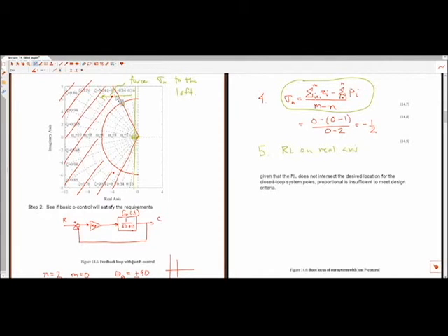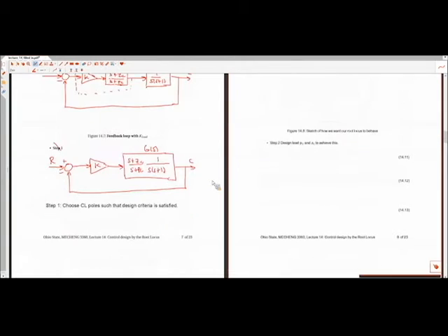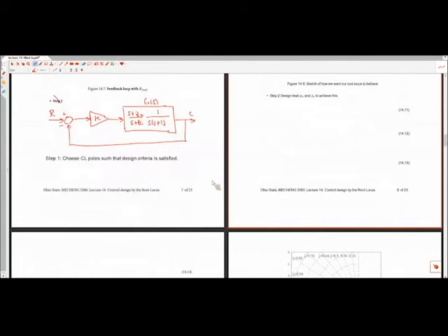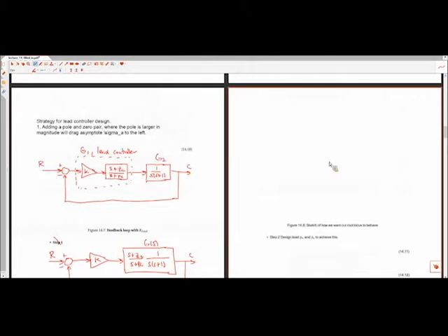All right, so make it easier on yourself. Make it easier on the graders when they're working on these things to choose nice round numbers, etc. So for this example, we're going to choose s equal to negative 4 plus 6i. There are nice integer values here. All right, so now we need to make sure the root locus goes through.